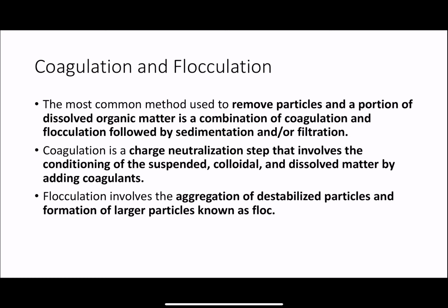Let's look at the first process, coagulation flocculation. What is the meaning of coagulation flocculation? Well, in coagulation, we are removing particles, and we are removing a portion of dissolved organic matter. Coagulation and flocculation remove particles and some of the dissolved organic matter. Of course, coagulation and flocculation should be followed by sedimentation and/or filtration.